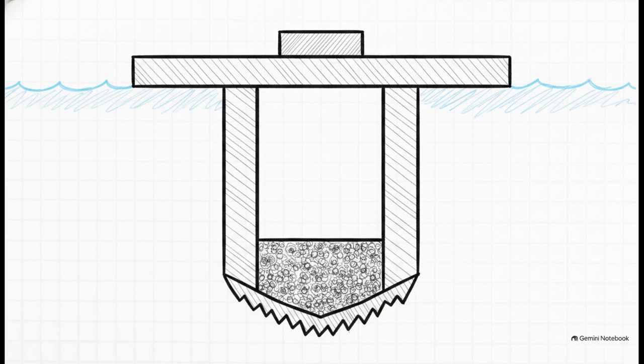Once the whole structure reaches the final depth, the bottom is plugged with a concrete seal. Finally, sitting on top of the steining, right around the low water level, is the well cap. This cap acts as a thick structural slab that takes all the weight from the bridge above and cleanly distributes it down into the well.